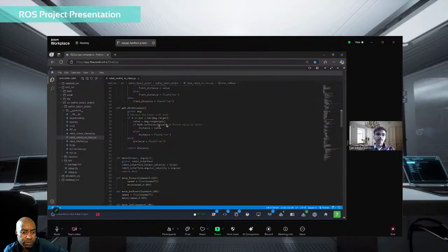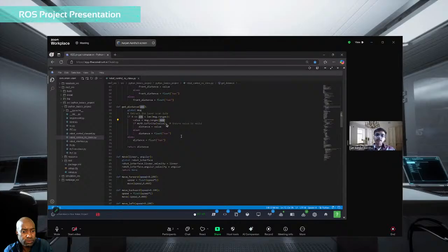This function I have made, which I mentioned earlier. In this variable, position, we enter the position of the lidar laser which we want to access. As we did first with 360, it was the front laser. When we pass the array from 360 to 180 or 360 to 540, it is the range from front to left and front to right.